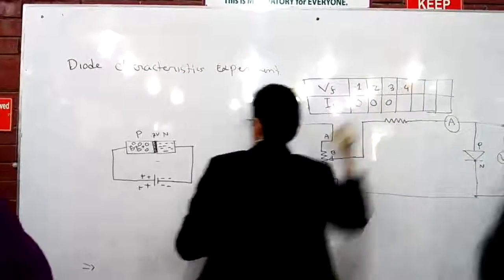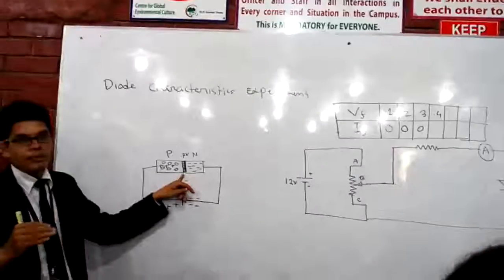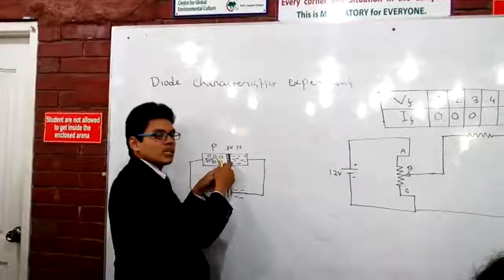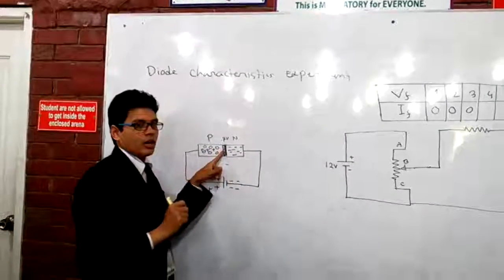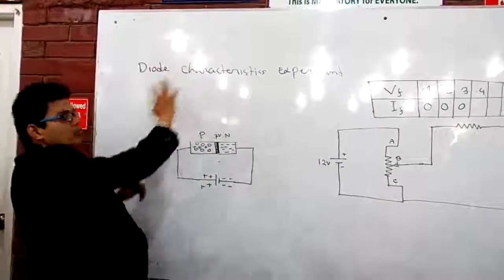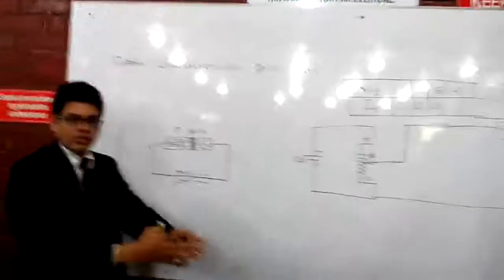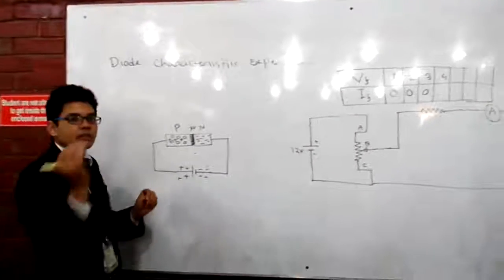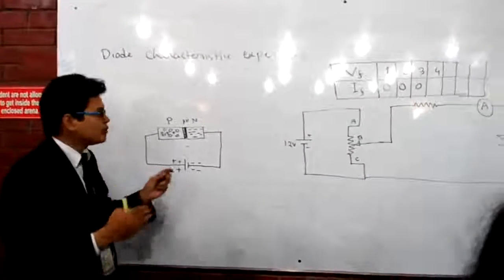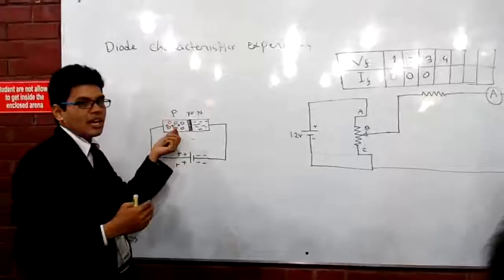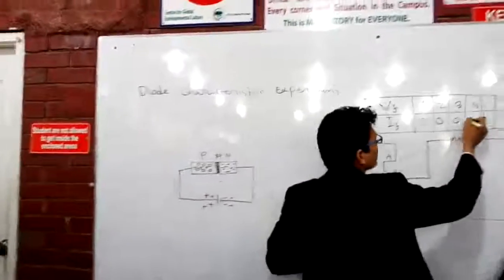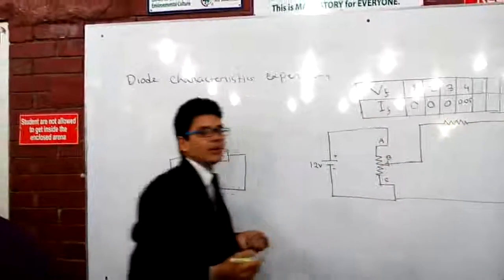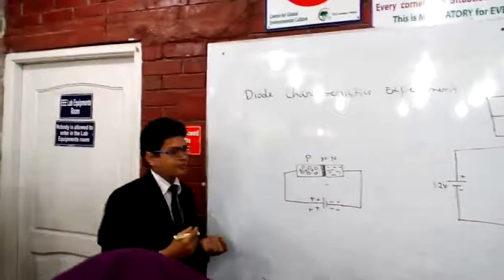At 0.4, listen, it is getting closer to 0.7, right? So some portions will be broken. Maybe a few bricks will come down. There might be a hole like this, right? So through this hole, 1 or 2% can pass. Which means a few electrons can still pass at 0.4 volts. So we'll have a very negligible current, maybe 0.05, something like a milliampere, which is a very small amount.